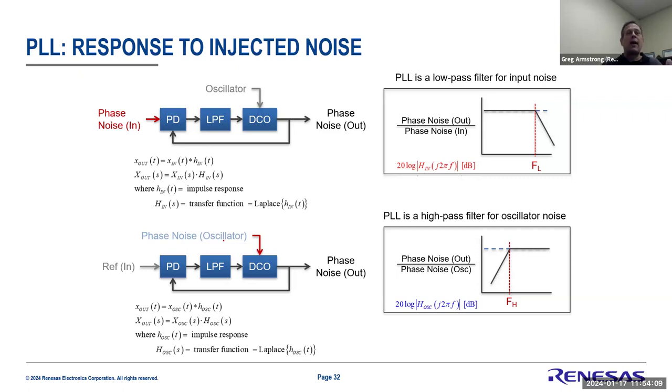And so this is why you sometimes have to find a balance between how long I want to average that noise, meaning how low I want to put my loop filter bandwidth, versus how stable my local oscillator itself is. You have to find this fine balance. A lot of organizations did this, and a lot of PLL vendors, the silicon timing vendors, can also provide characteristics of how to define your system, to say what's the best cutoff.